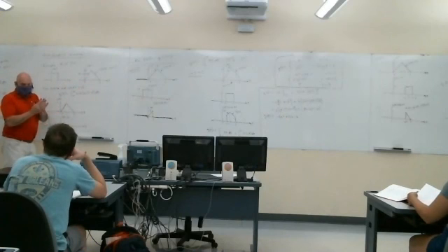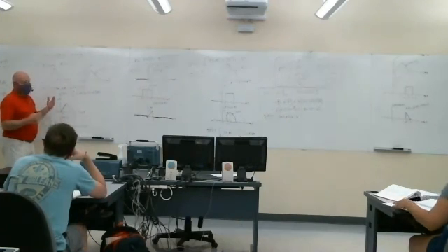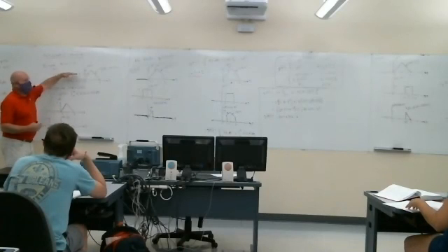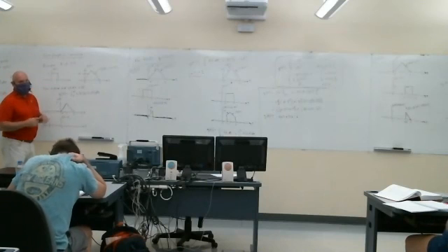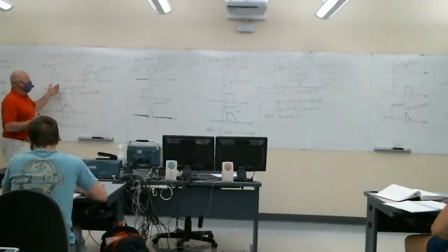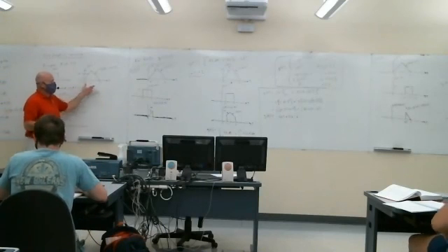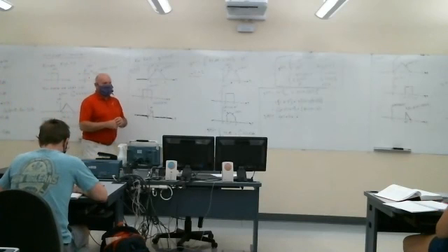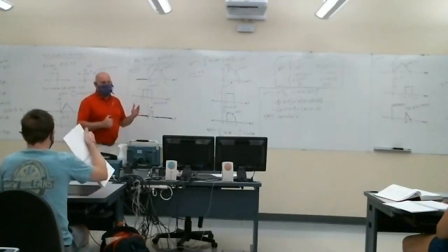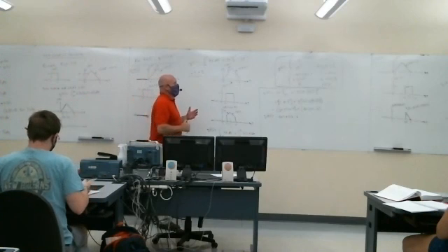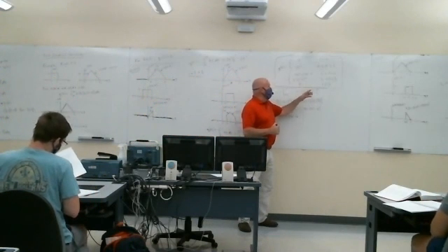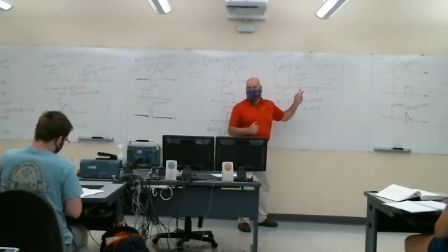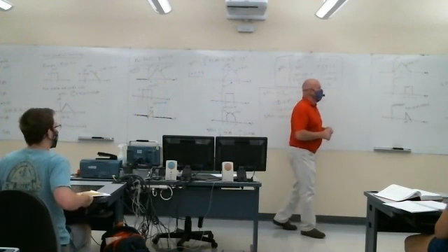So if we're dealing with finite width pulses, that's not always the case. I mean, this could be a unit step, which has infinite width, and then the output would have infinite width. But in this case, this has width 1, this has width 2, so the result has width 3. And it does. That's another check. You want to check at the inputs, at the end points, these transition points. That's how we found that error. Okay, that's always a good check.